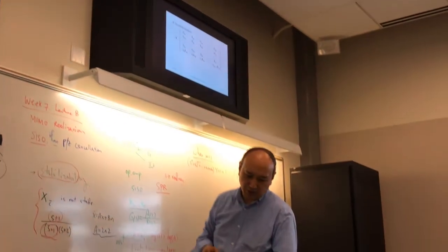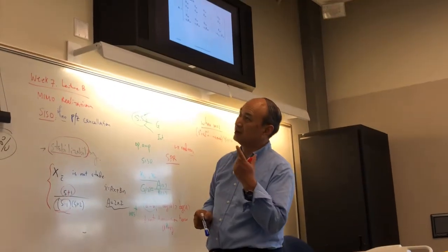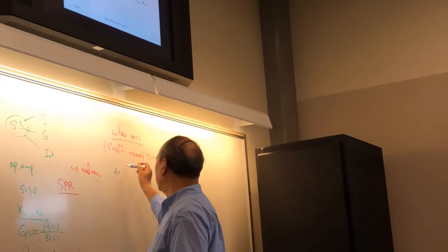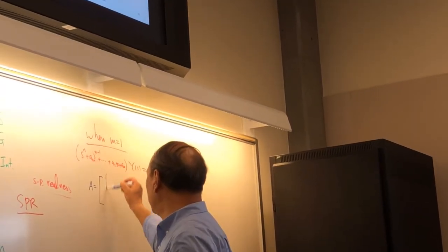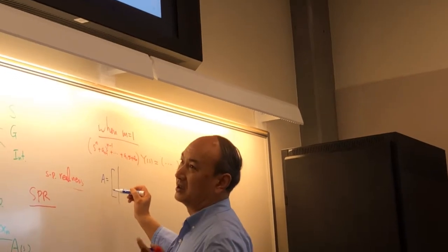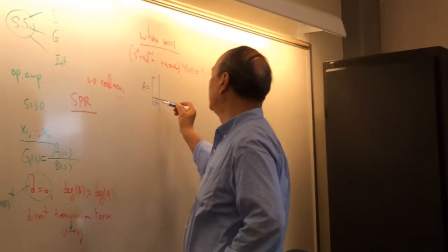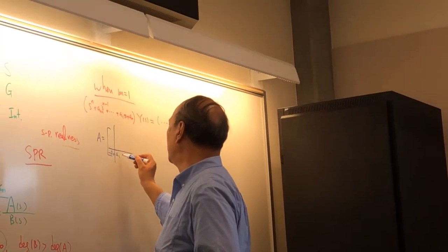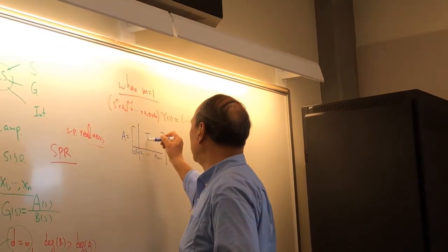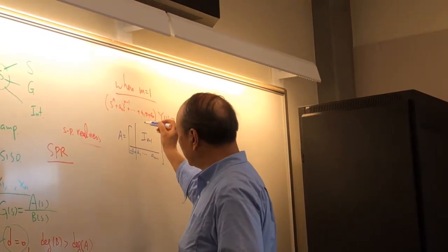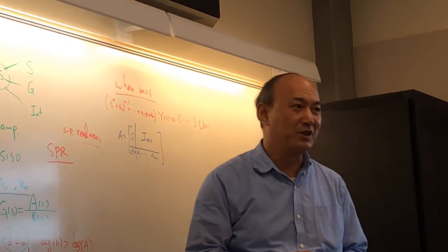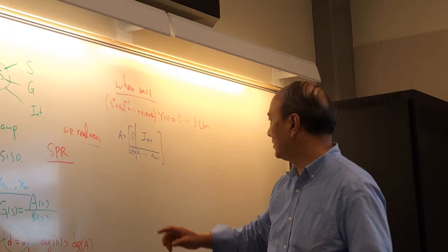So then when I do this realization, you will see the A matrix in the controller form, we usually write this way. So this one is minus a0, a1, until a n minus 1, and we usually put n minus 1 in here. So this one is 0. That's the way we usually write it.